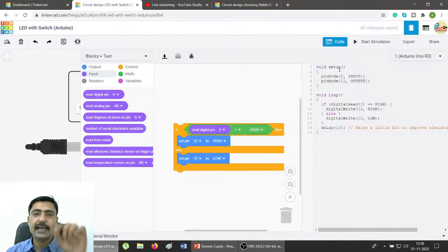There are other things also, but I will not tell you now. In the next session, we will be discussing other options which we can do with these pins. Right now, I'll tell you that we can use these pins as inputs and outputs, but we need to define them. By default, all the pins are considered as input pins. But if we want to use any pin as output, we need to tell the controller that I am going to use this pin as output. Baud rate is also defined there, and I'll tell you in the next session. Baud rate is the speed to transmit the signal. So to define the initial environment, baud rate and pins, we use setup.